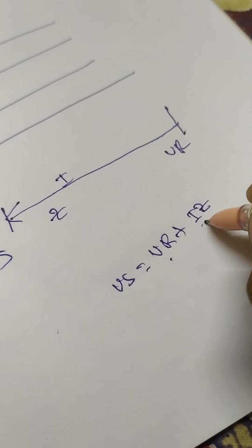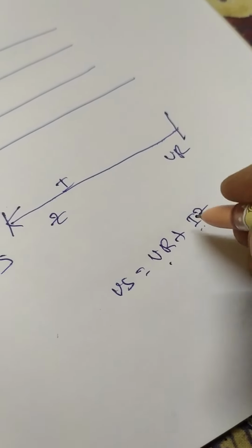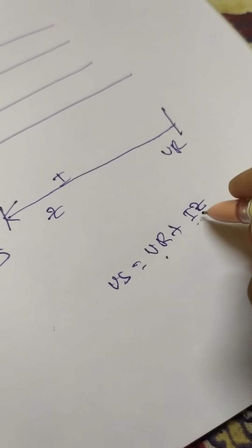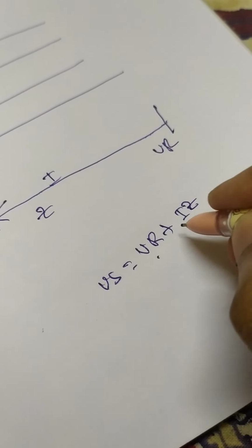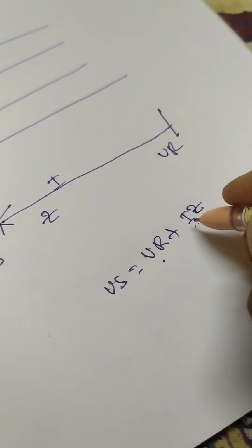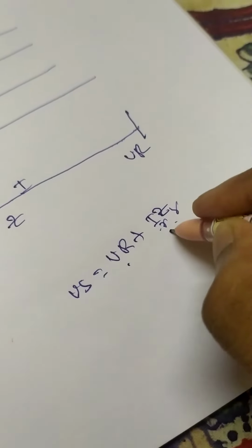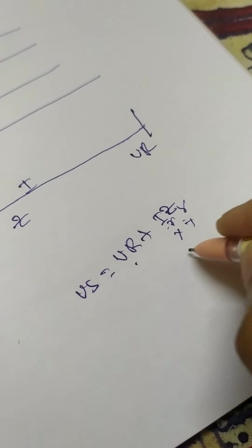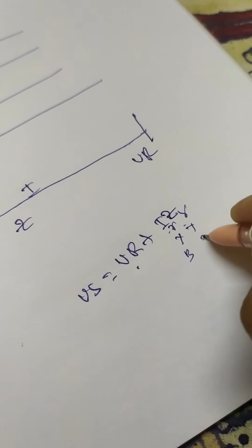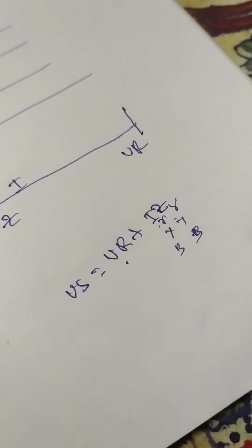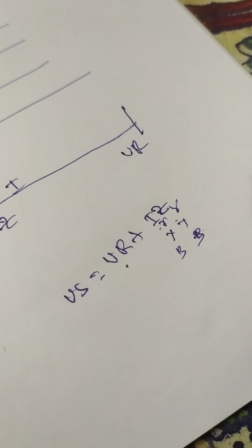This represents the voltage drop with respect to this impedance. To calculate for phase R, we simply put IR and ZR; for Y phase, IY and ZY; for B phase, IB and ZB.